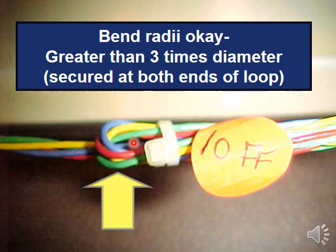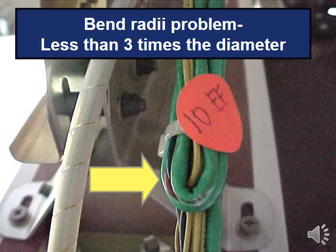Okay, so this looks like it's okay. It might just barely be enough. So here, let's look at our blue wire. Here's your outside diameter. I'm going to just eyeball this one and say we've got 1, 2, 3, maybe 3.5, the outside diameter for this bend radius. So it looks like that's okay. It's not crushed too much. But now look at this one. It's basically folded in half, just like we saw earlier. So please be careful about the bend radius.